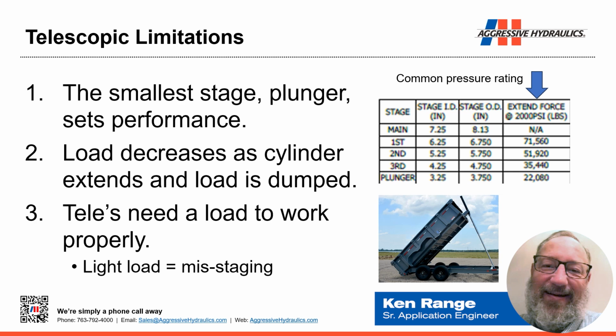You look at this performance chart, and really the most important thing to pay attention to is the smallest stage or the plunger. It really doesn't matter if the first stage can lift 71,560 pounds, because if that is the load that you're trying to lift, the second, third, and smallest stage aren't strong enough to move it. So what's the benefit of a telescopic cylinder?